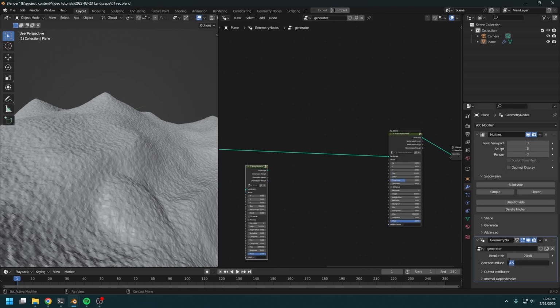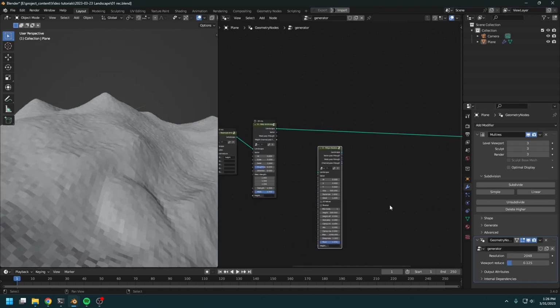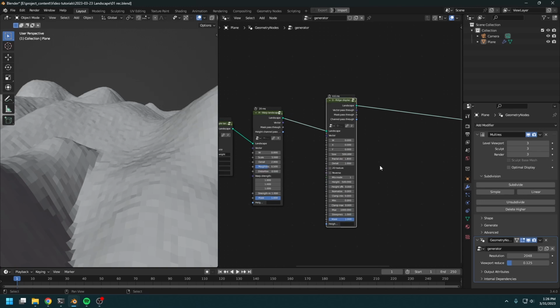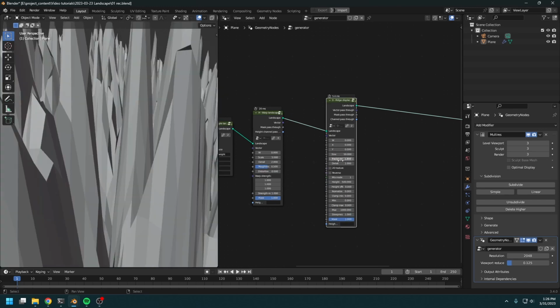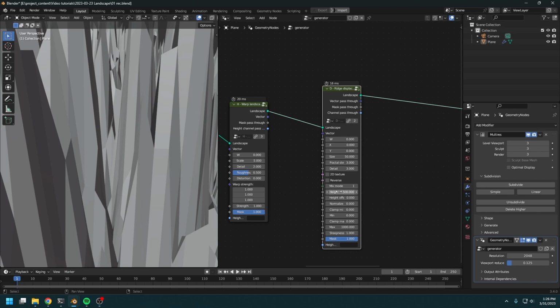I'm just gonna lower this down to 0.125 so that we have a 256 by 256 landscape. This is gonna be a lot faster. And just drop the ridge in, and for the ridge size, let's set this to 50, and detail step size to 3, and the detail level to 3, and this maybe 10.